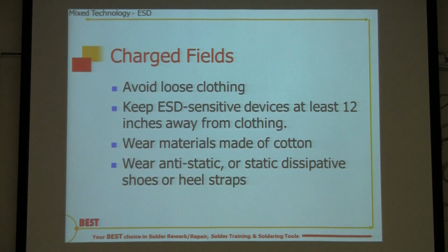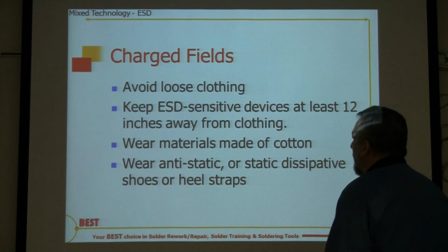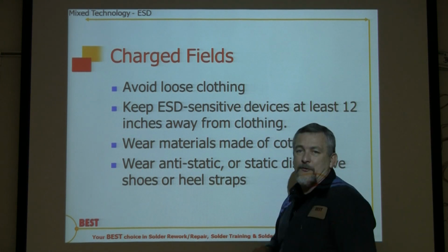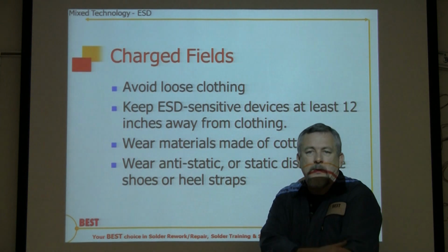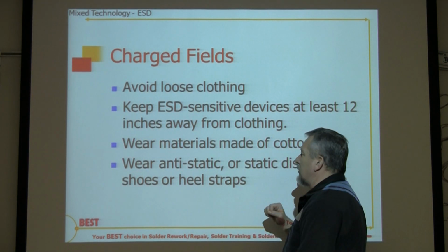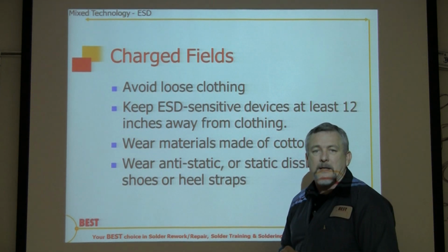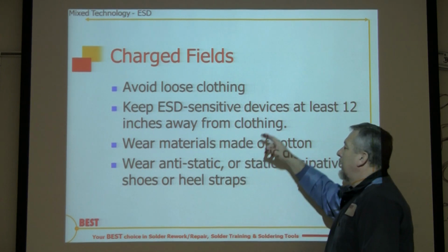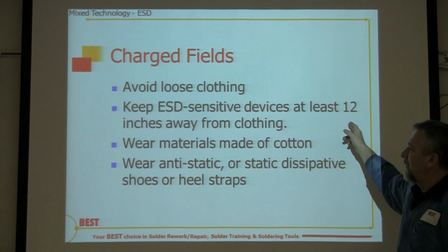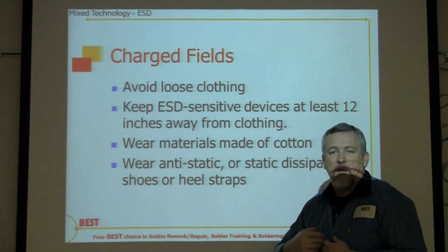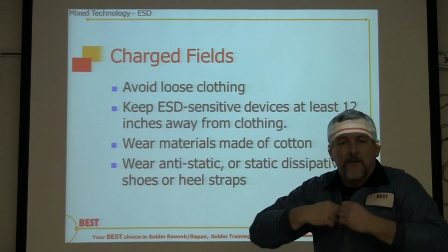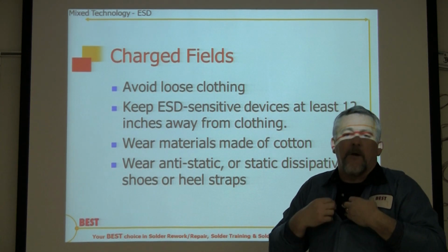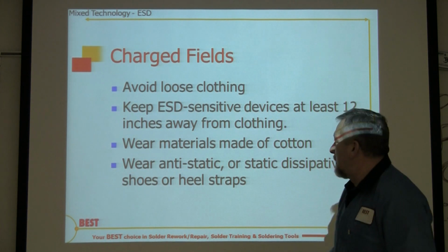Charge fields. What do we mean by charge fields? How can we create a charge? Very simple. How do we avoid loose-fitting clothing? What do you mean? Remember that rubbing, that movement that goes around? That can cause static electricity or generate it. Keep ESD-sensitive devices at least 12 inches away from your clothing. Why? Because remember, this moves around and stuff, but I've got a jacket on instead.